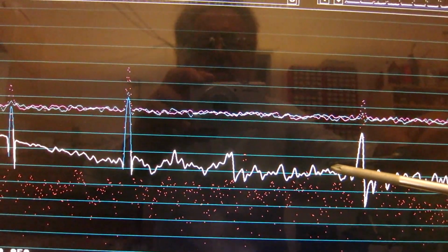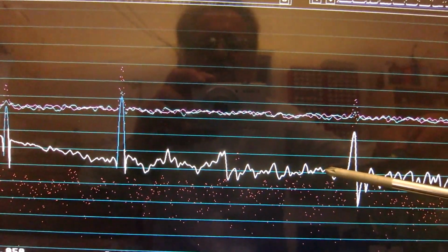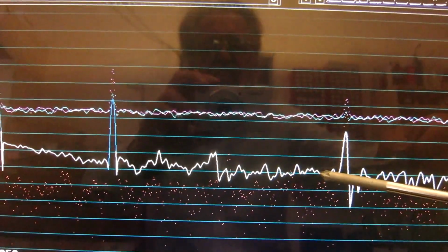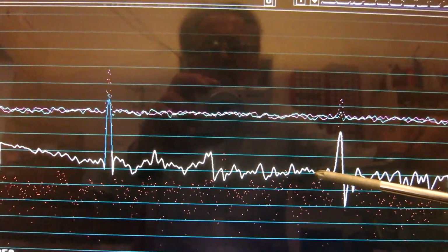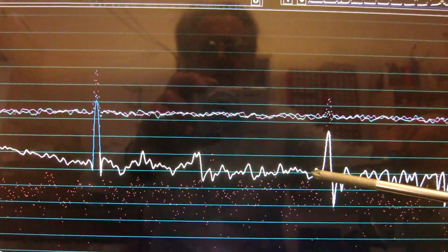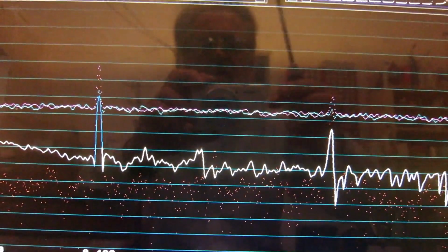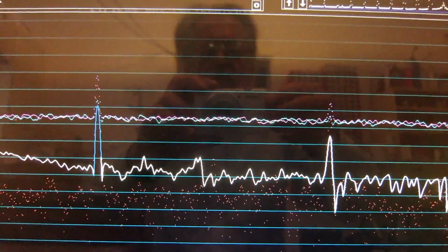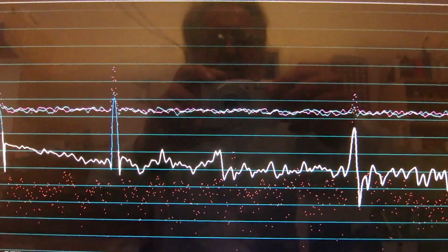On the input to the 2-channel receiver, there is a hybrid. And what I'm measuring is the difference of the noise in the dummy load, and that is on the other side of the hybrid, as compared to the signal source, which isn't 50 ohm anymore because it comes from the clipper.